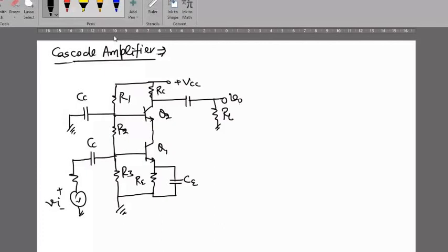You see here, this is the emitter terminal. You are collecting the output at the emitter terminal, and you are utilizing that output of one transistor as the supply to another transistor Q1. Okay, understood? It means if you see separately, this circuit is just providing a loading network to transistor Q1, and the rest is like potential divider biasing.